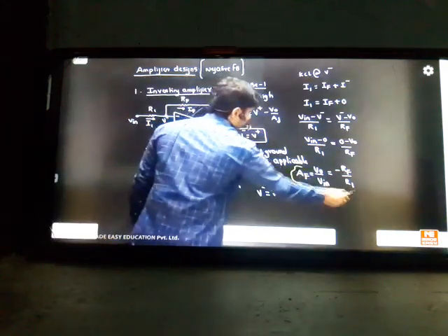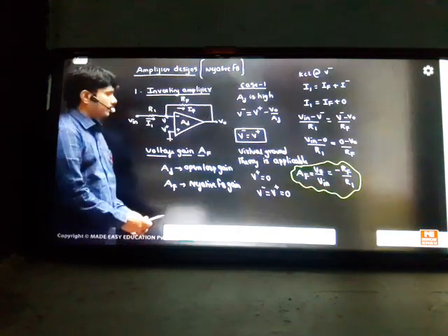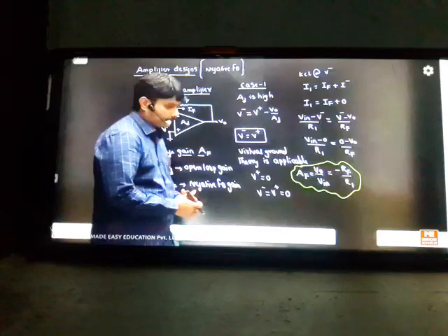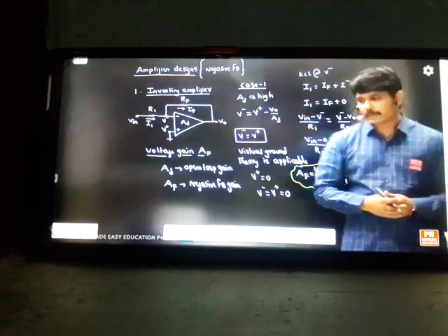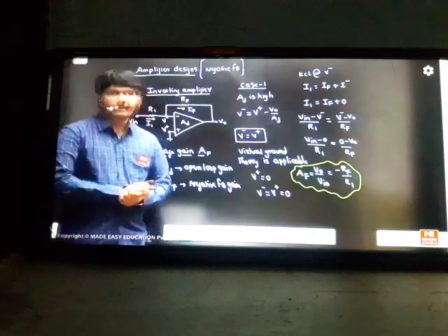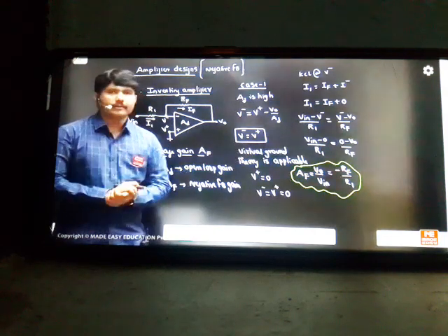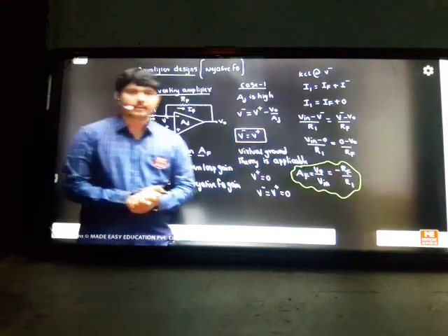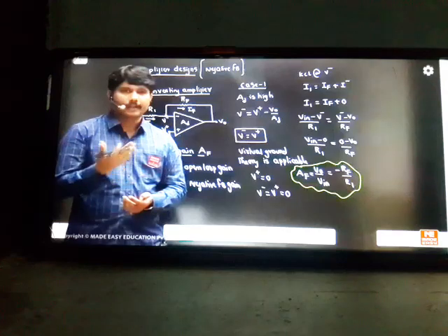These are the best formulas for op amps. Throughout your life, this formula never changes, so practice these standard formulas from now on. Now, closed loop gain. Some student asked me why the negative feedback gain will reduce. Maybe this formula will explain. The negative feedback gain does not depend on your AD, it depends on the resistors. So with resistors you can adjust it in such a manner that you get low gain or high gain, whatever you like.